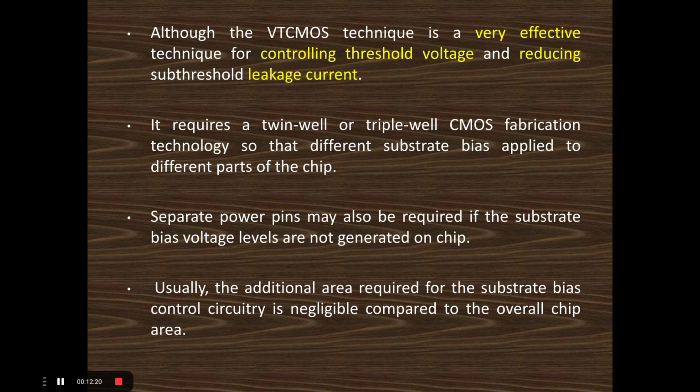That is a little bit complex for us. Separate pins may also be designed for the corresponding substrate bias controlling circuit. That is somewhat difficult, and it is costly because we have to route the corresponding lead terminals from the substrate.